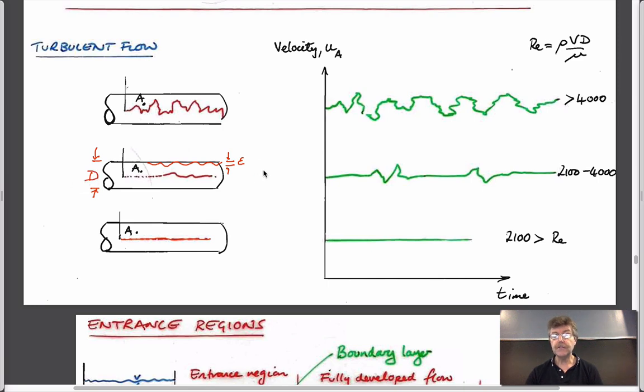In terms of similitude, the two parameters that define whether the model looks similar to real life are the length to diameter ratio and the roughness. It could be a length ratio, but you could imagine that the roughness would have more of an effect relative to the diameter, and it turns out that's just the case. So these are the two geometric terms which control behavior. In addition to that, it's controlled by the Reynolds number, which is a density, a velocity, a length scale, and a viscosity. So it's the ratio of inertial to viscous forces.